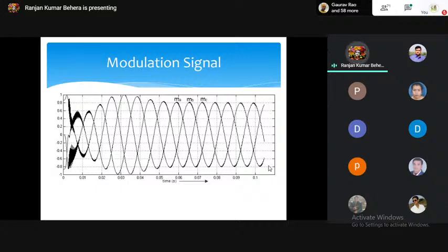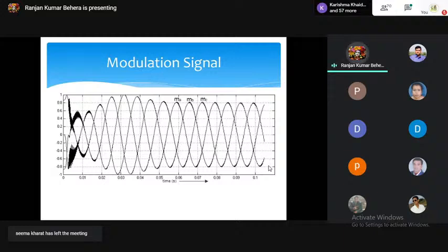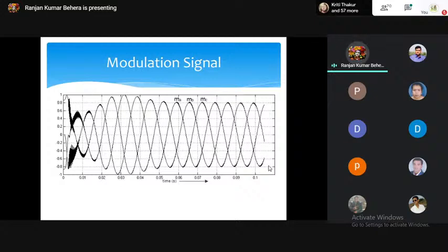So why does this chattering take place? There are many causes actually. There may be high frequency noise due to the switching of the converter, which propagates to your control circuit. Second, it may be due to line stray inductances, where there may be a resonant effect that may also create more electromagnetic interference. Or it is due to harmonic switching, meaning at the same time they try to stabilize the system very quickly.